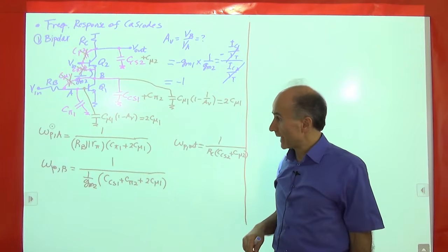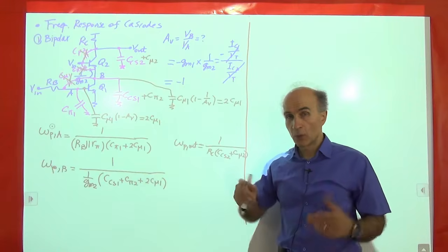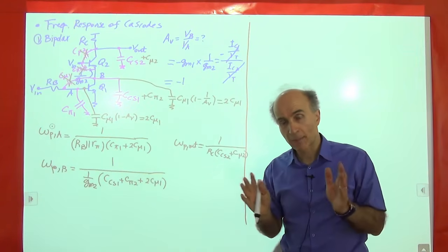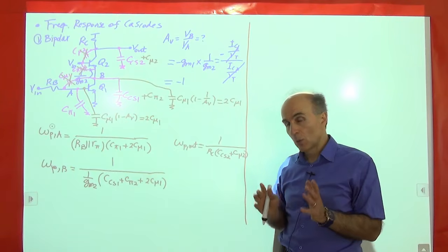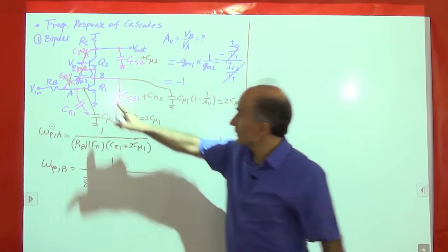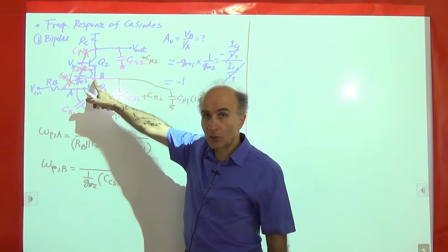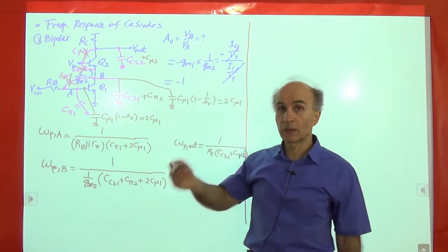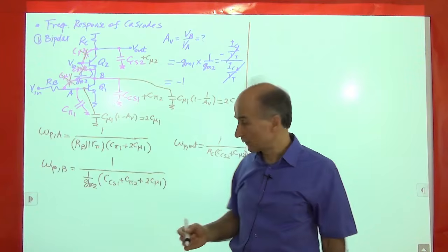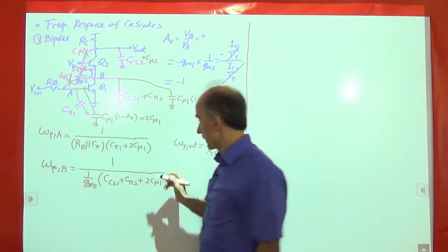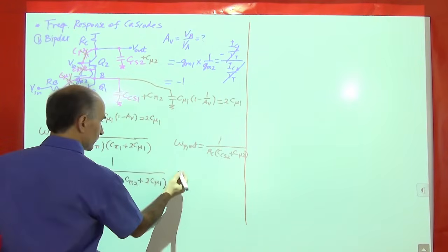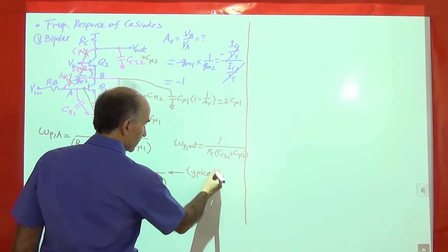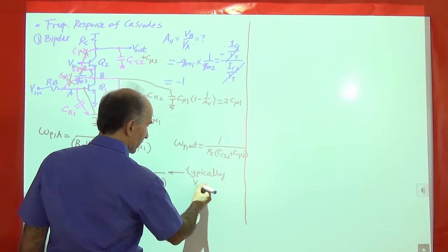All right, so you may ask, we have 3 poles, which one tends to be the limiting factor as far as the bandwidth is concerned? Well, typically, the pole at this node, which we call the Cascode node, is very high. So typically, that frequency is not the limiting factor. So this would be this one here, right? So typically very high.